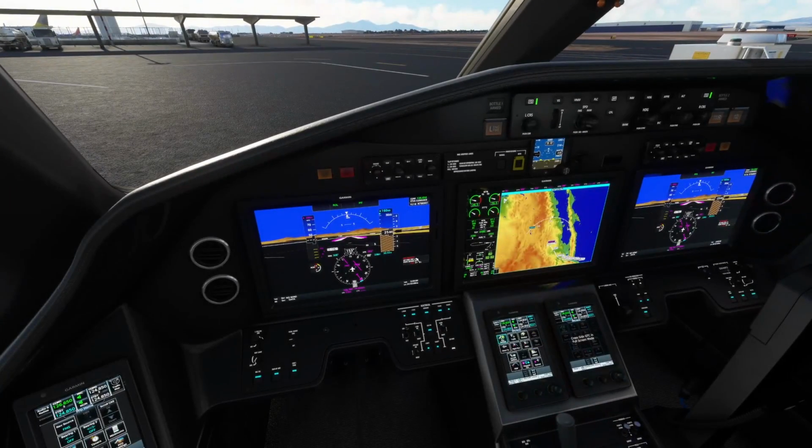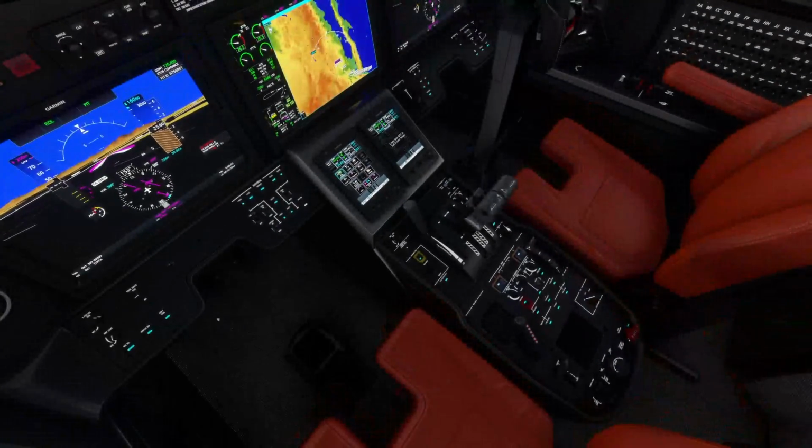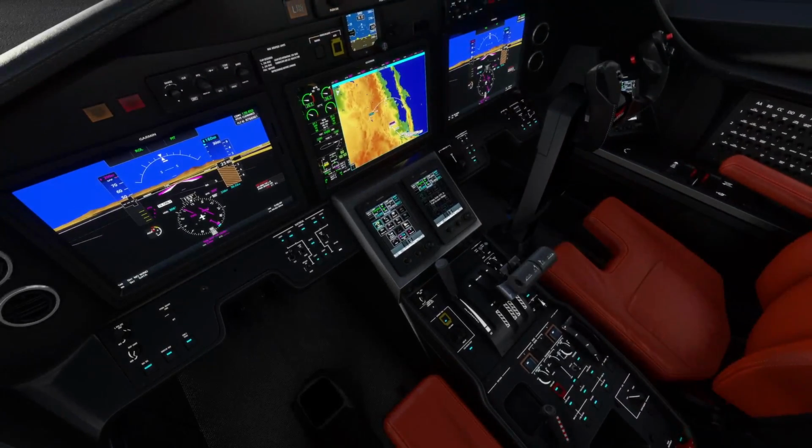No takeoff config. That is because we still do not have the flaps down. So honestly, if we want, we could go ahead and set the flaps, but much like with the TBM, I believe standard practice is they don't normally drop the flaps until they're just about ready for takeoff, simply because they're so close to the ground. You don't want any debris kicking up and pegging the flap surface. But, I mean, I suppose in simulation, it's all up to you guys.